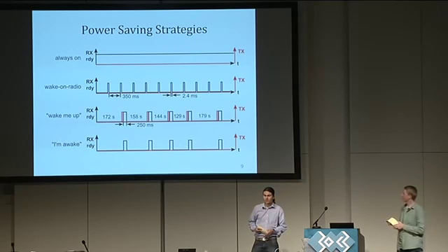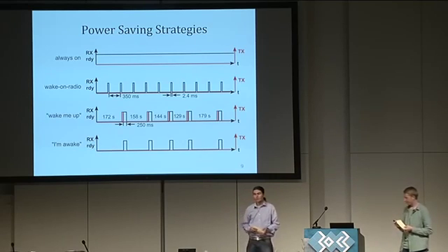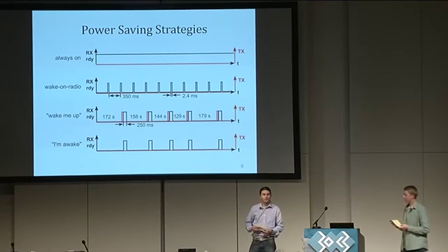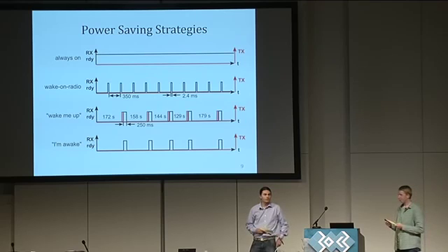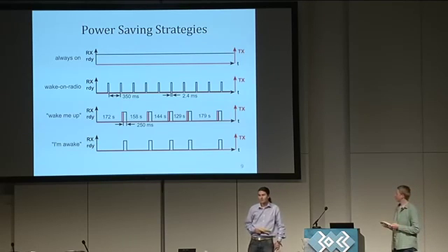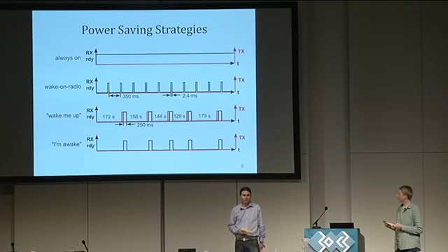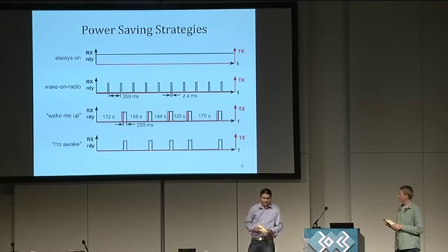The device wakes up to receive ready mode for 2.4 milliseconds, and after that it falls asleep for 350 milliseconds repeatedly. So it can react to packets almost immediately.